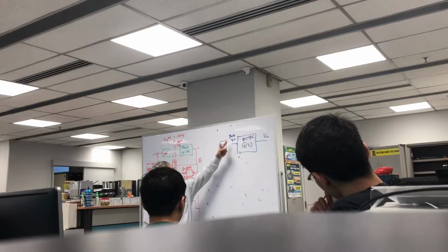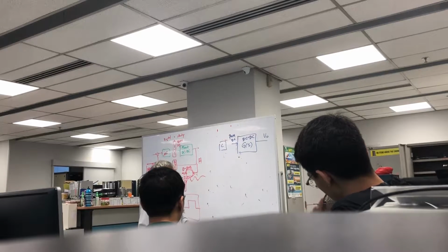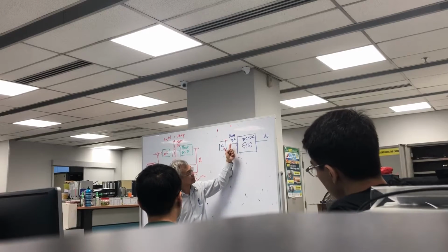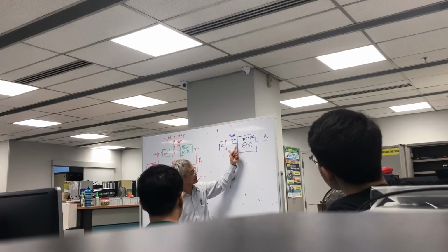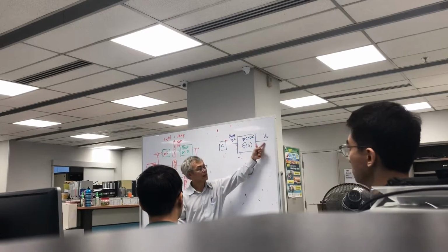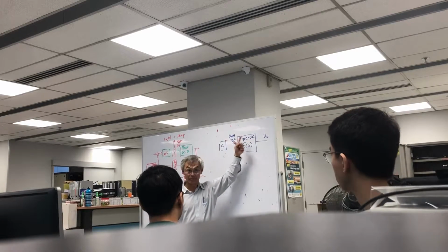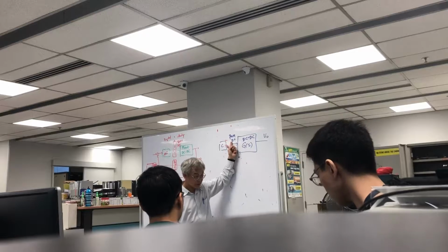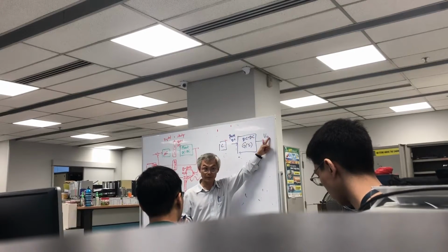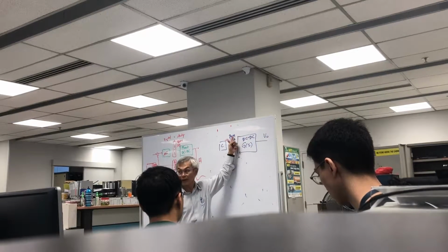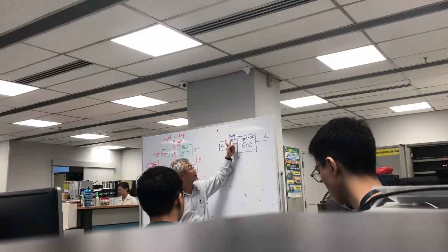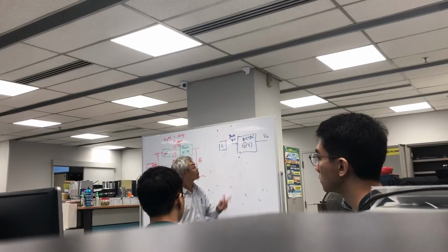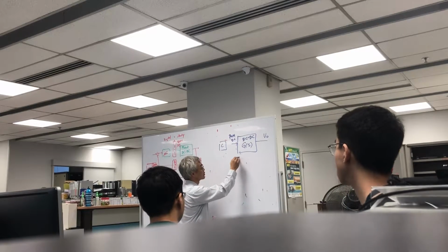Okay, so with this now in mind, clear. The first question you ask yourself for open loop test is find out the input-output relationship. So what do you have to change the output? So now we agree that you need to change the duty cycle of the PWM. Because look, in your tutorial it is always this.